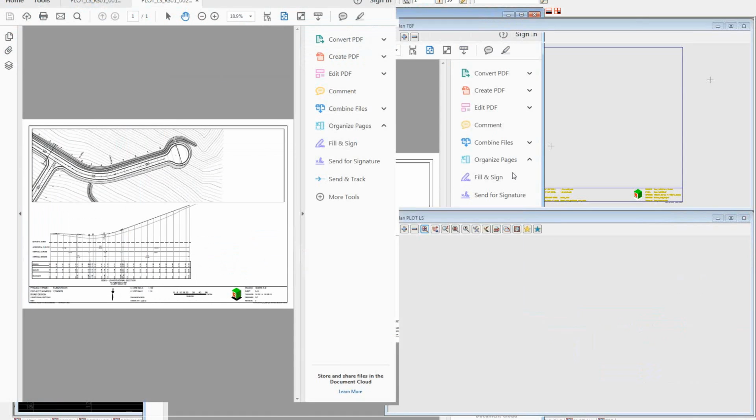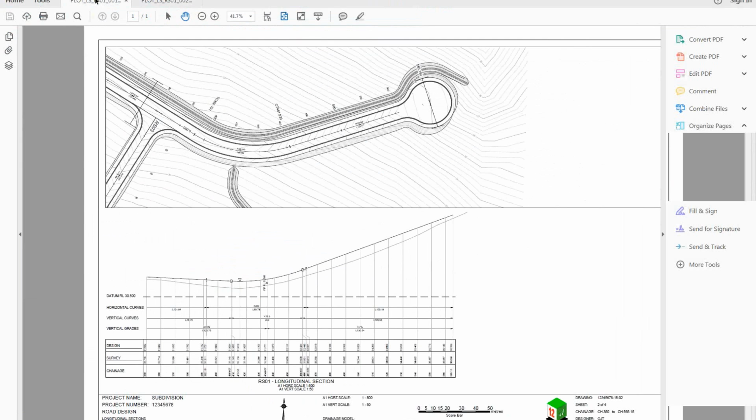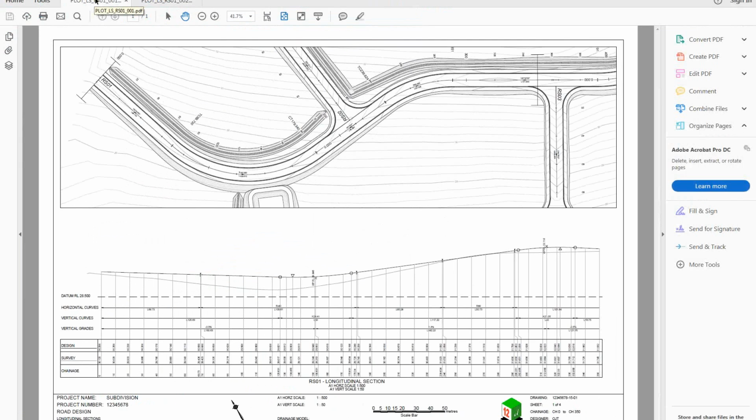Now I've got a new version of Adobe Acrobat Reader that puts the different sheets on tabs here, and I can see sheet 1, and it's all been mapped into grayscale and black and white colors apart from the logo there. The PDF color plotter only plots in color for the standard 12D colors like we've used in our logo here. All the other colors we'd use were various grayscale things, or various plot parameter file colors for the text and things like that get mapped to a black pen or some kind of grayscale pen. So the drafting standard is actually pretty good there.